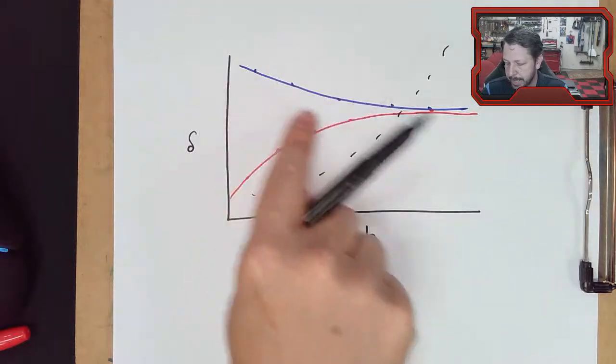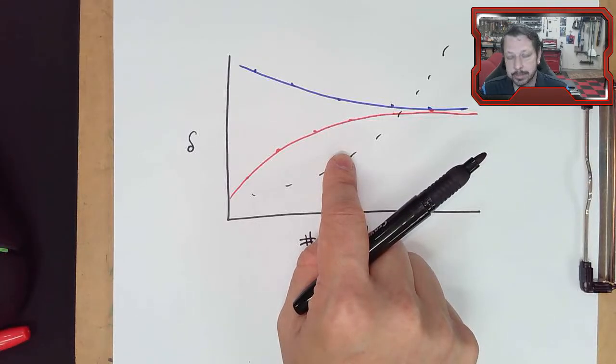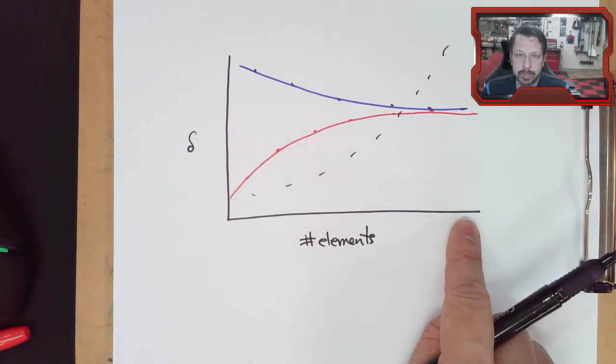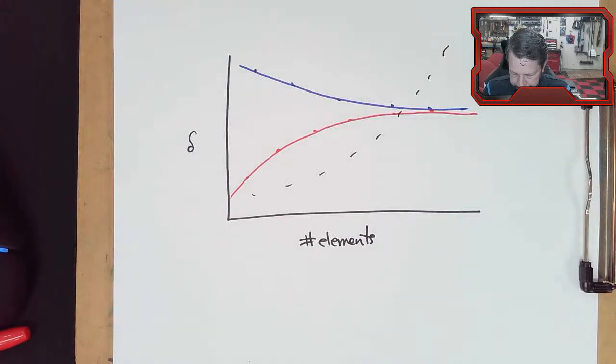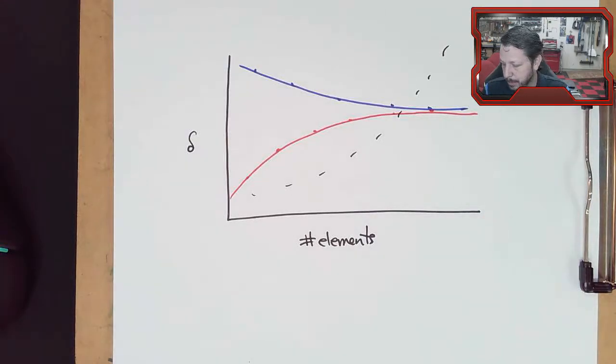You'd want to see, this is one way that you can verify a model with its own self, because you might be tempted to think, well, my computer is really powerful, I've got a supercomputer, I'll just run the number of elements up to the maximum I can do, let the simulation run for an hour, and that should be right. But even in that case, you want to make sure that the model itself is predicting the right kind of behavior.